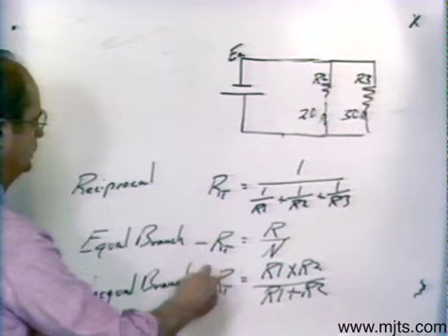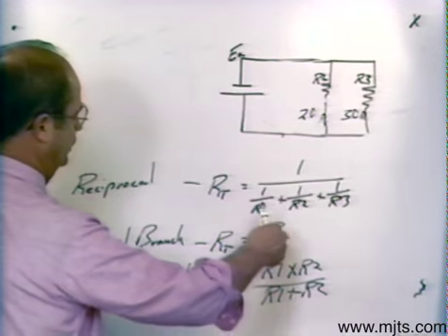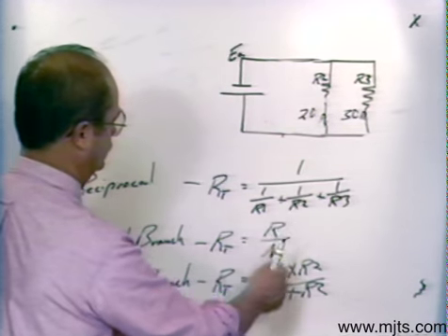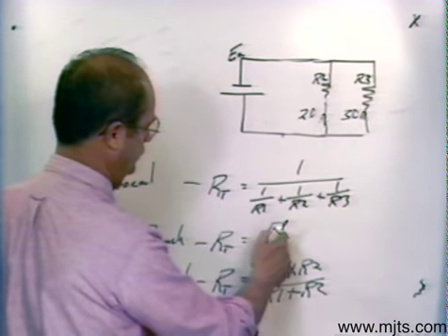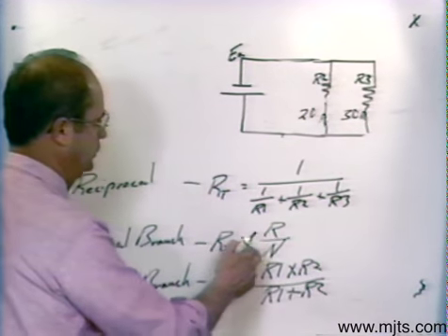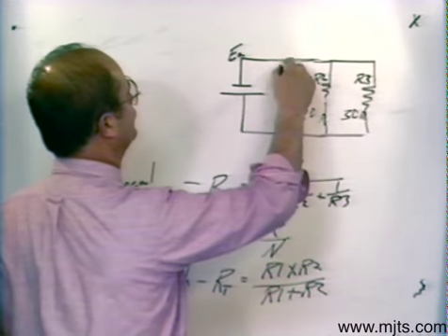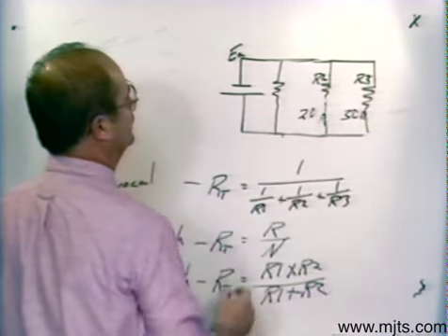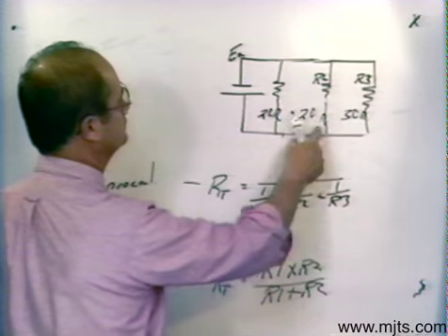I'd remember those. It makes your work a lot easier a lot of times if you know that when your resistances are equal, you don't add up your resistors, you take your value of resistance and divide it by the number of them that you've got, and you'll get your total resistance. There are times where you may have three resistors, and maybe, for example, I have two 20s.